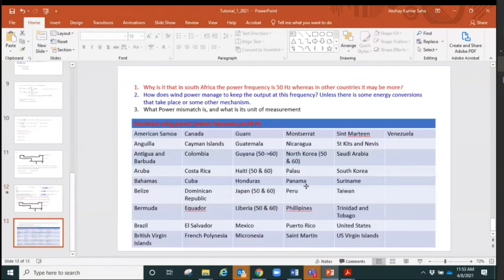So sir, that injected value is measured? Yes, that's measured. That's what each and every generator is supplying, because that's the real value. And these calculated values are intermediate values. When you are done with power flow, the operator will control the generators connected to the swing bus, so that the calculated value is reflected back in the generator P and Q values.